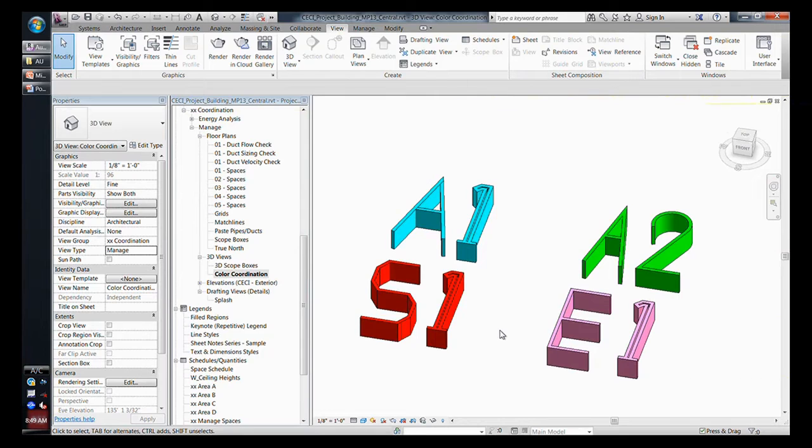Another cool thing that I believe helps people really quickly see where things come from. When you're in a mechanical view, all non-MEP geometry will appear in gray if the mechanical view is set to mechanical discipline. That's what happens. So say you're linking the structural, you're linking the architectural, you're looking at an object. Where is this object coming from? Is it from the structural, from the architectural? It can be confusing. And this is where my guys can come in and really quickly navigate through the model and visualize, okay, this is coming from this guy, this is coming from that guy.